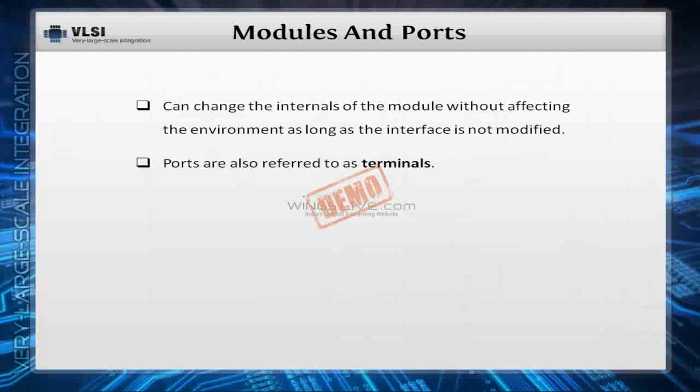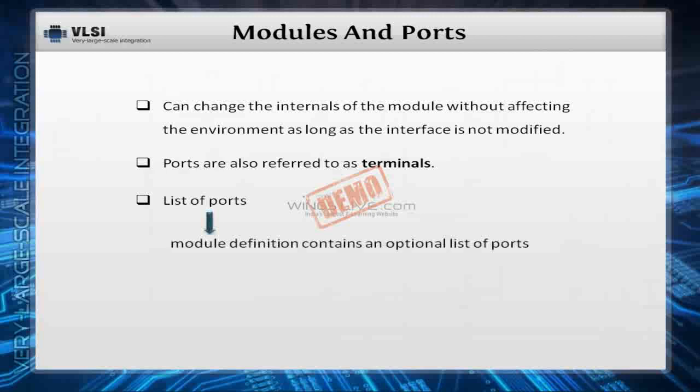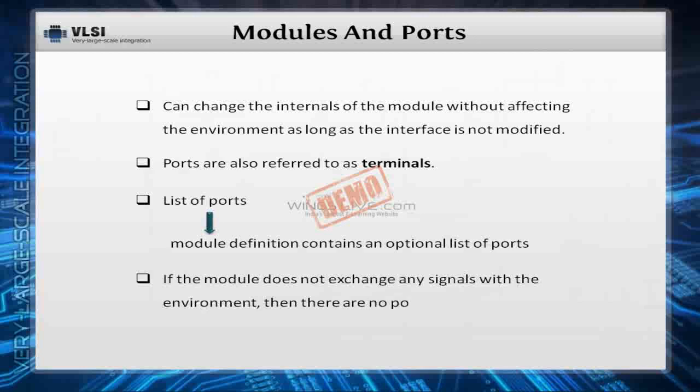Ports are also referred to as terminals. Now, we've got a list of ports. That is, a module definition contains an optional list of ports. If the module does not exchange any signals with the environment, then there are no ports in the list.